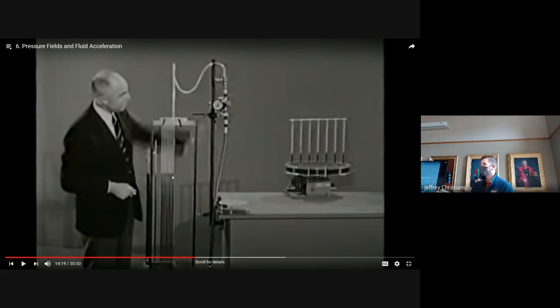Any ideas? What's it going to do right at the center? We've done this a whole bunch before, right? You have fluid flowing, and it's going to crash into that disc and come to a stop. So what's the pressure going to do? It's going to go up to the stagnation pressure, right? So that should be above atmospheric. But then what has to happen? Outside is atmospheric pressure, right? It's one atmosphere. So you have high pressure at the center, but then for the air to get out, it's going to spread radially out of that disc.